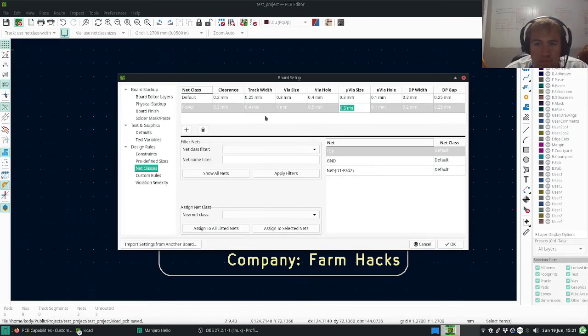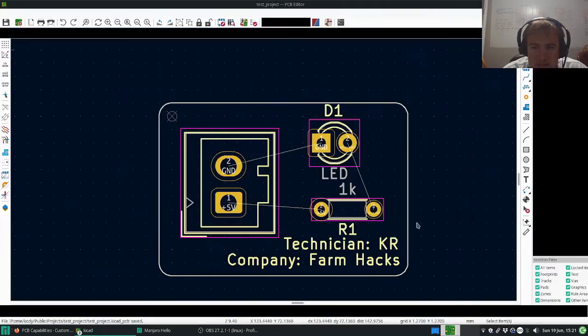And now, once you make your new net class by pressing that button and changing all those values, you can go over here, click there, click this down button, press power, and do that again, power, and then you can click OK.